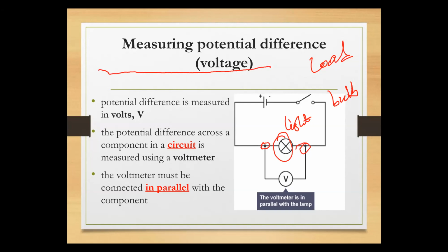That electrical wire is your load going like this. So the wire goes in and the wire comes out on the neutral. For your potential difference, you plug one leg here, one other leg there, across, in parallel to your device. Here is your voltmeter represented by V. Here is your device, a light bulb or load. See, it's in parallel, connected across it. So the voltmeter must be connected in parallel with what? With the component.